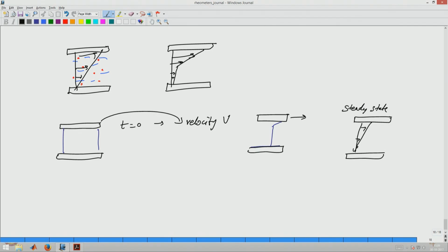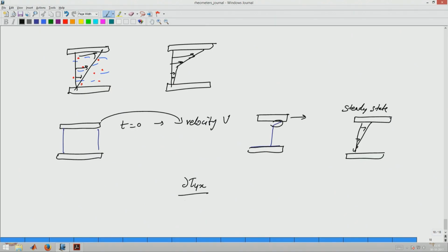applied on the material. Let us say, given that you are expecting some part of the material to flow, that means the stress is higher than the yield stress. Because if you remember, the linear momentum balance or equation of motion for a parallel plate geometry, the Cauchy equation, says in this case del tau yx by del y is equal to 0, which means tau yx is constant. There is no assumption involved in terms of which type of fluid; it can be viscoelastic, it can be just viscous. So, this is the equation for all materials.